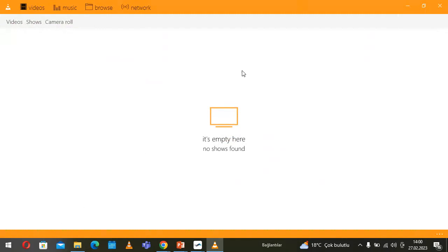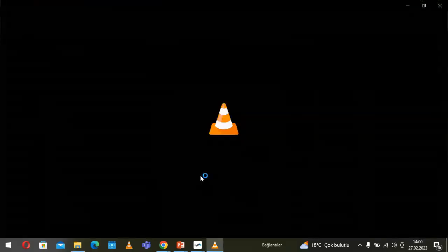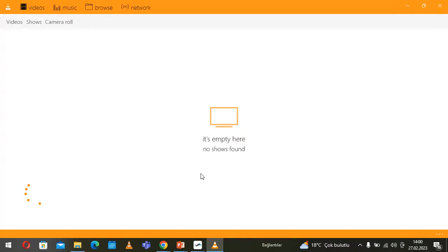So you see, once more, they start at the same time. And the restrictor flow control valve is adjusted the same for both of them. But on the right side, we have load, and on the left side, we don't have load. And you see the external loads affect the speed for the restrictor.